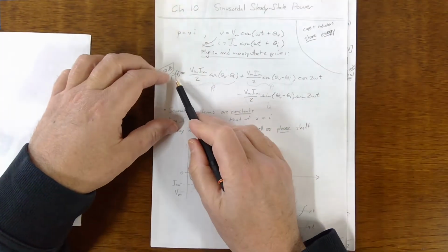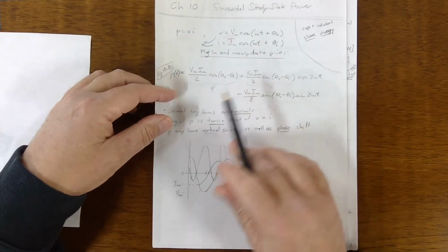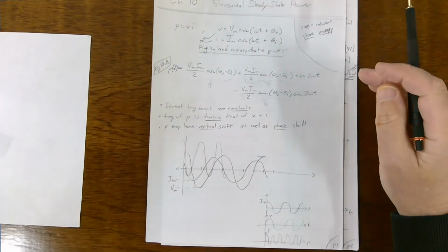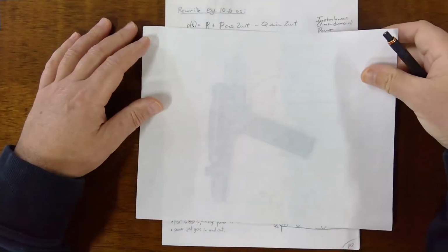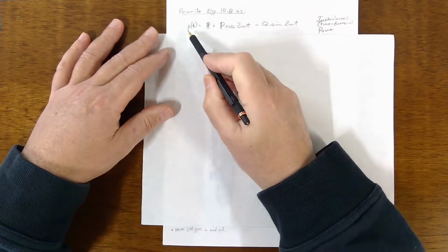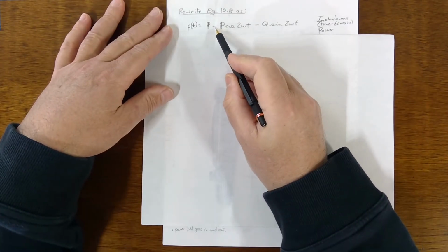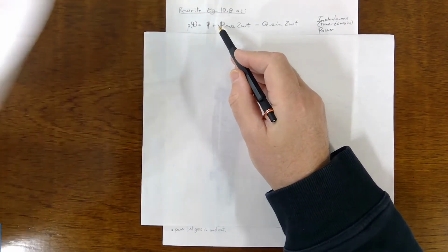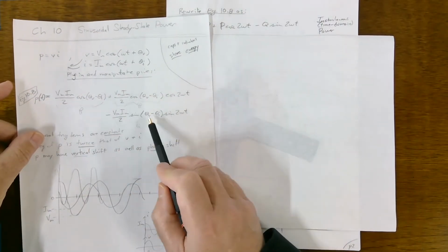So that's the reason they wrote this p of t time domain in this form: because it leads to phasor domain. In phasor domain, we can simplify the time domain equation, and we get this big P term, which was all of this stuff here, and then the big P term again, and then the Q term.